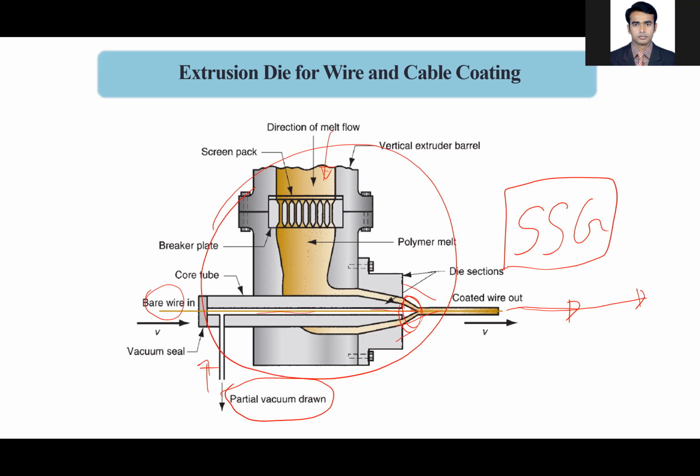You'll get a pipe. To attach the plastic with the wire, you have to use vacuum, so that the plastic continuously gets attached with the wire, and the wire is drawn with the plastic attached to it, and the cooling is applied.